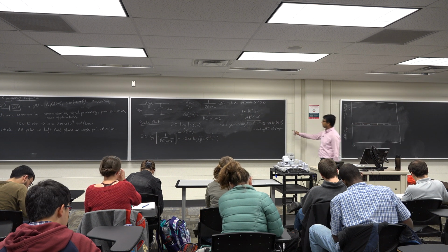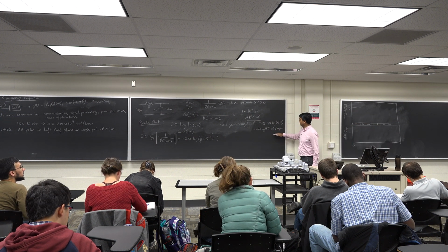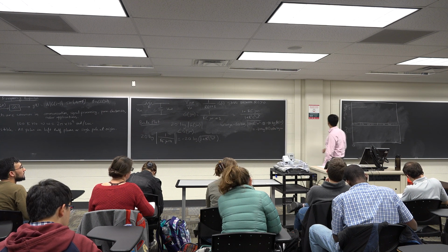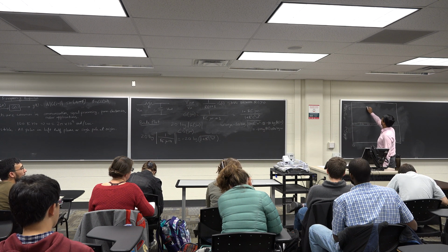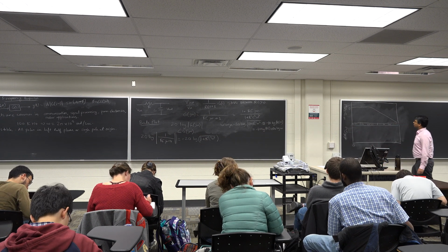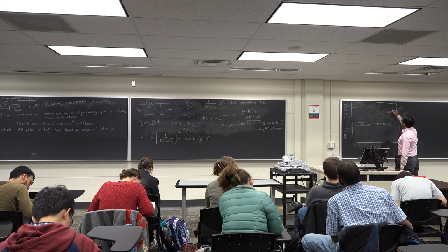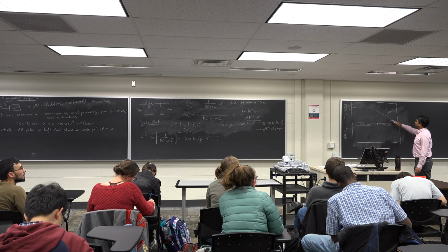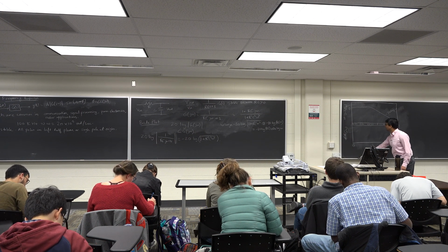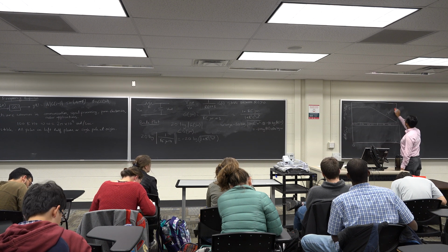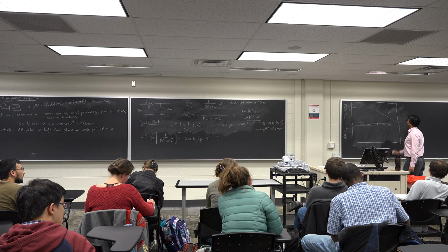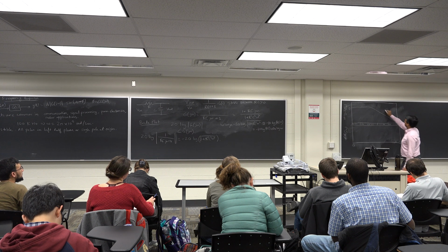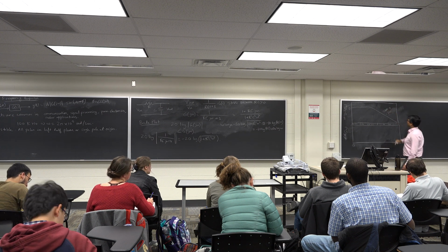Okay, so at very large values of omega, of course this term would be small in comparison to 20 log omega, and this term will dominate the whole expression, and you will see that the curve actually goes down according to minus 20 log omega. So the slope of this curve is going to be minus 20, because our x-axis is the log omega axis.